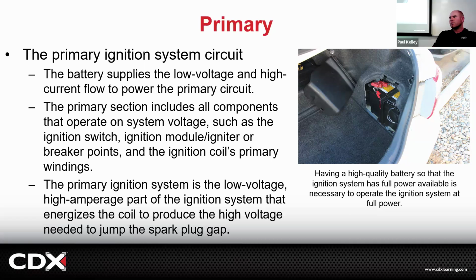But think about it. If your system voltage was low, would it cause a misfire on one cylinder? No, it would cause it on all of them. So that's one of the reasons I like for you to understand the system a little more overall. Because if you jump on the forums and they're like, "Oh, you got a misfire? Yep, definitely check the battery." And it's sort of like, well, 5 cylinders are working fine and one is not working fine. Yeah, technically the battery's kind of part of the primary, but part of the primary for all 6 cylinders, not one. See what I mean?